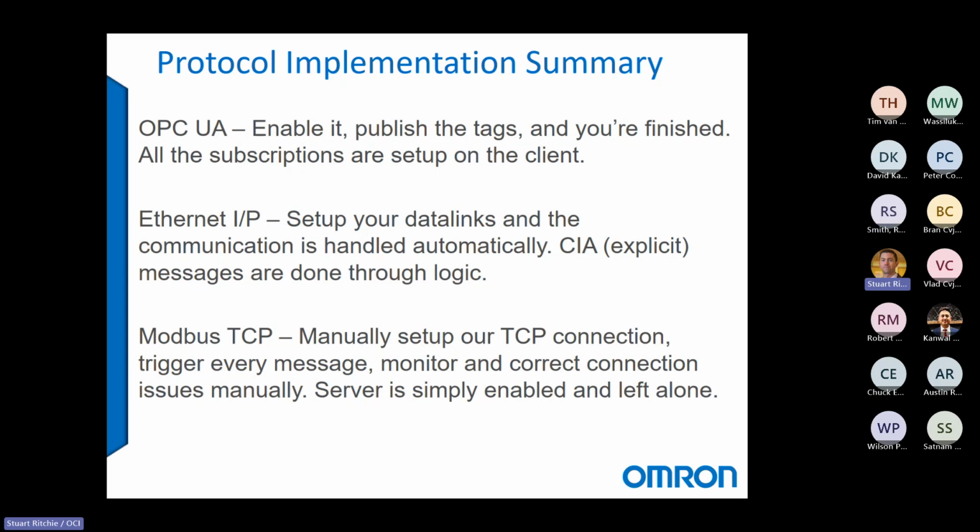plant, you probably don't want to set up implicit connections with every one of them, since you're just looking to read the max current from time to time. If you get an update once a minute, that's not a big deal. But if you wanted to save on implicit connections, because every PLC is limited on implicit connections, that could be a use case for explicit messaging, but it won't be fast, that's for sure. You'll have to set up a messaging carousel and cycle through them all.